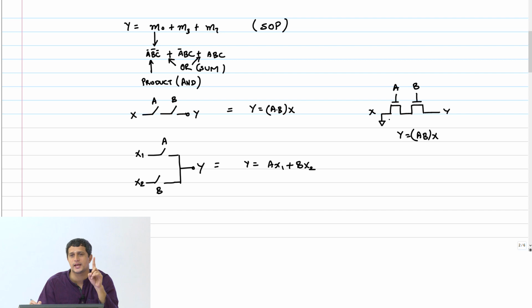And if the signals A and B go high, which means they go to VDD, then both NMOS transistors will turn on. The 0 from here will appear here, and that 0 will also percolate to the output Y. No problem. On the other hand, if I connect this to VDD, then what will go through from here to here is VDD minus VT, and further from here to here is also VDD minus VT, right? Whereas for 0, it goes to ground,